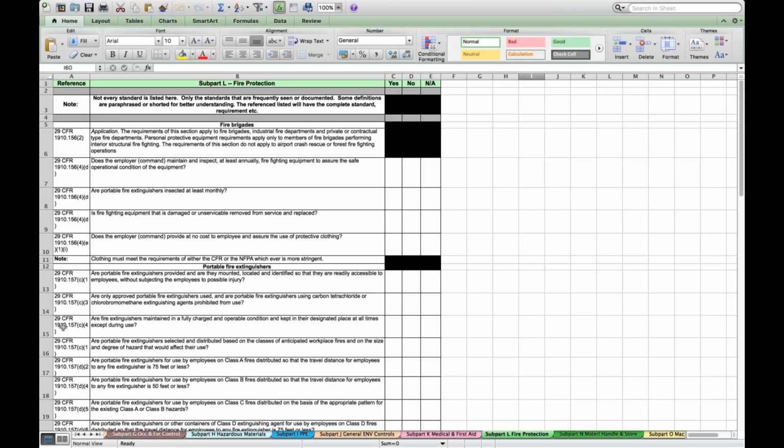Okay. All right. And then what's the next thing we're gonna do? We're gonna assess that risk, right? We're gonna do a risk assessment on the facility, and we're gonna break the items down into different types of risk that we may be exposed to, and things that we're gonna want to check and make sure of. Hey, what kind of catastrophic hazards are we gonna have? We're talking about catastrophic being loss of life, right? A fatality. And then also, what kind of critical injuries or illnesses might we have? I'm talking about severe injuries or illnesses or severe property damage as well. And then it could be marginal. It could be something like a minor illness, an injury, or some property damage. Negligible, basically being low hazard, okay, or nuisance, right? But still, of course, still a hazard as well.